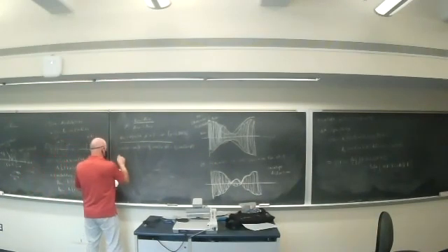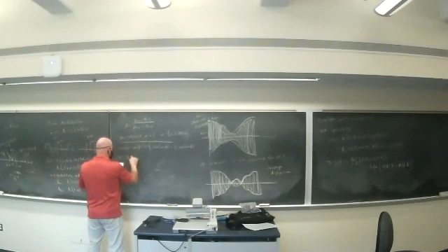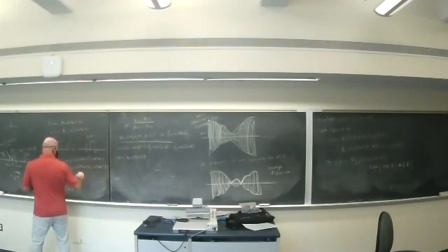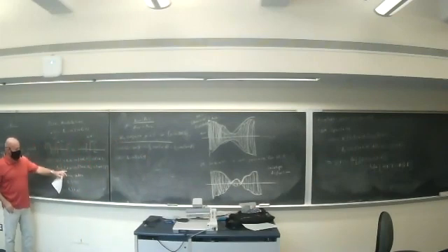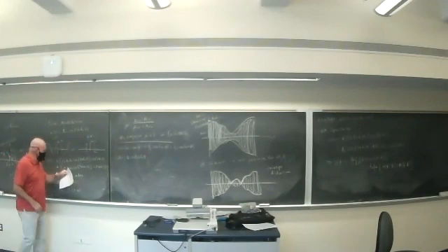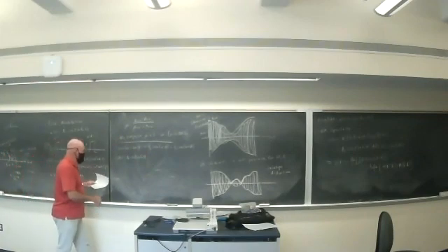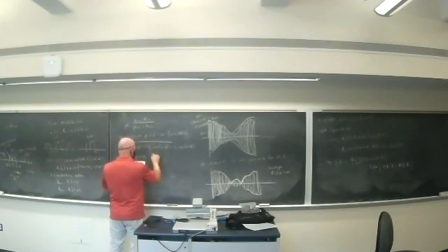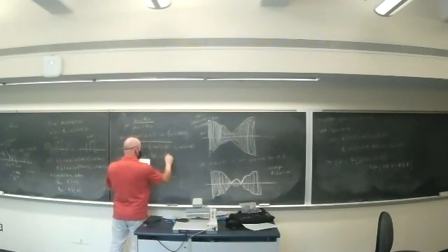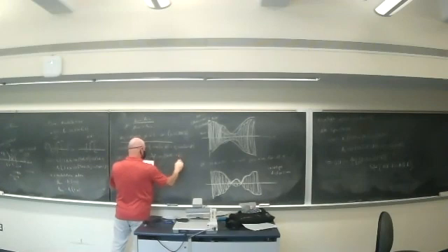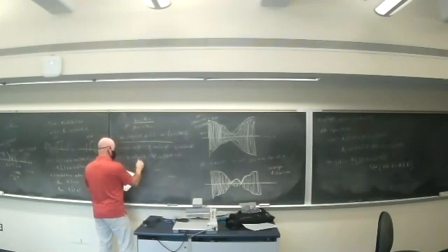So that means S of t here for tone modulation, if I expand all this out, I've got the AC cosine of 2 pi FCT term, and then I'm going to have the product of these cosines. So that becomes AC mu over 2 cosine of the difference. So that's 2 pi FC minus FM times T. This is actually the carrier term, which contributes an impulse.